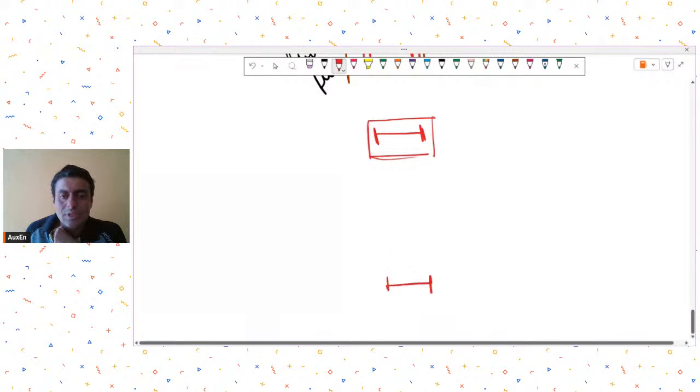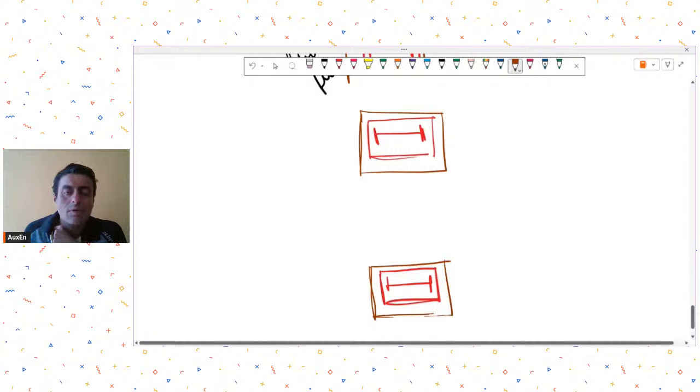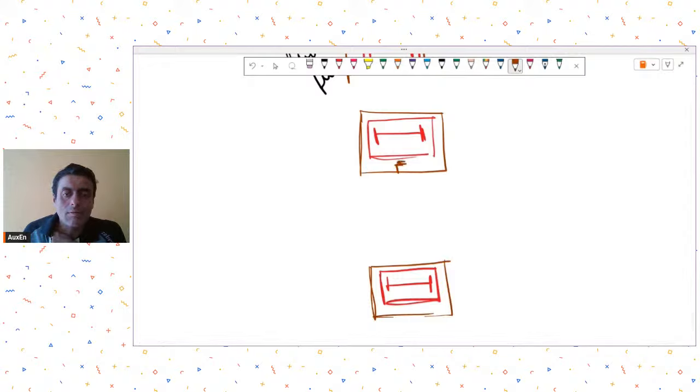And suppose due to certain requirements you cannot take the brick wall outside, you have to take it inside itself. In such a case, what you can do is you have a pedestal over here, let's say, and you have a concrete mullion column cast over here separately, and you have your brick wall like this, and maybe you could continue with this, but I have introduced this mullion column.